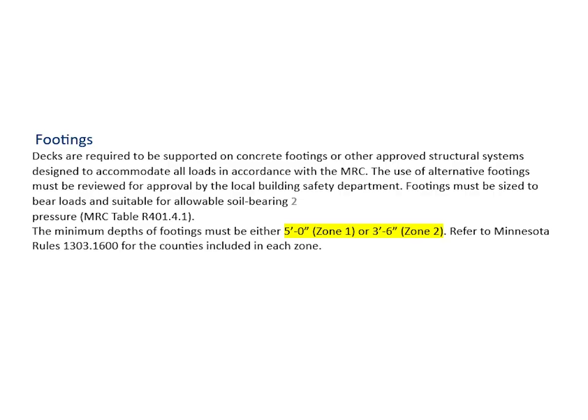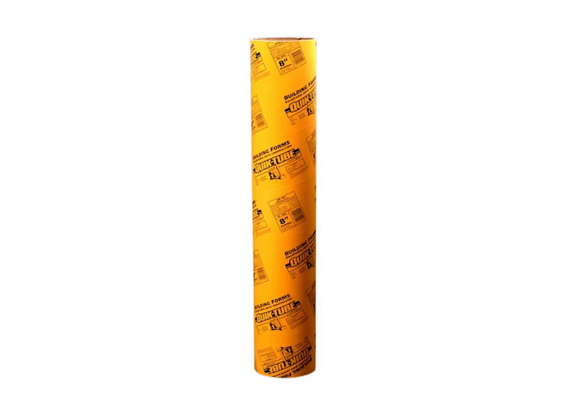The below-surface depth of the footers is predicated on your location in Minnesota. Where I am, Zone 1, I'm required to have 60-inch deep footers. The footer uprights will be through tubes such as this. For post or beams not to exceed 4 inches side to side, the tubes will have an 8-inch diameter minimum.